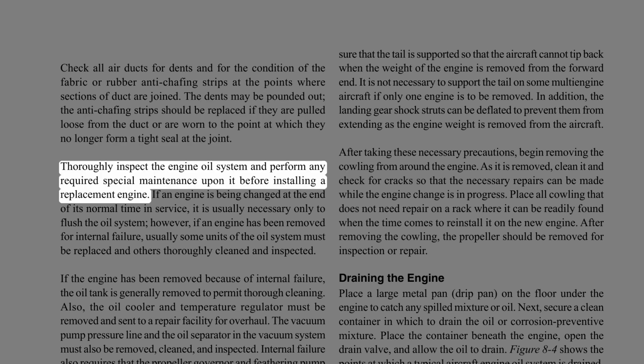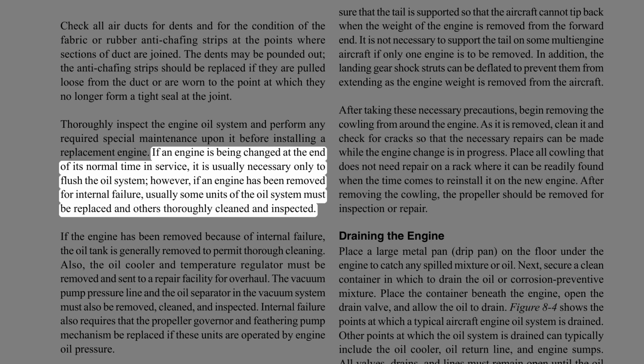Thoroughly inspect the engine oil system and perform any required special maintenance upon it before installing a replacement engine. If an engine is being changed at the end of its normal time in service, it is usually necessary only to flush the oil system. However, if an engine has been removed for internal failure, usually some units of the oil system must be replaced and others thoroughly cleaned and inspected.